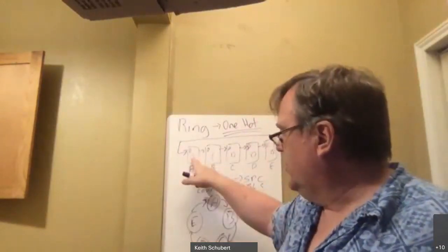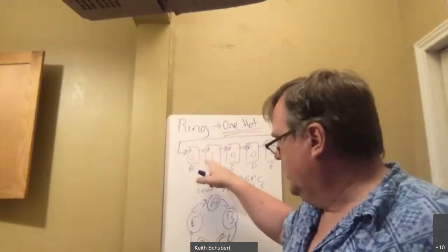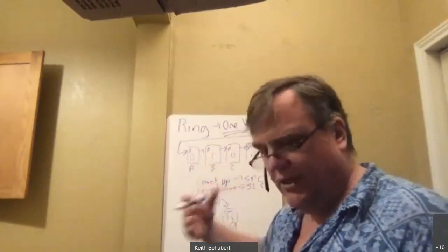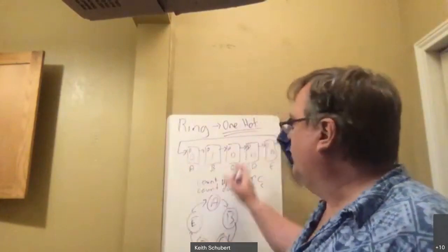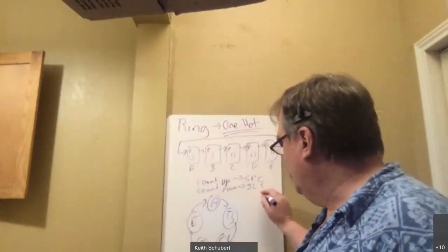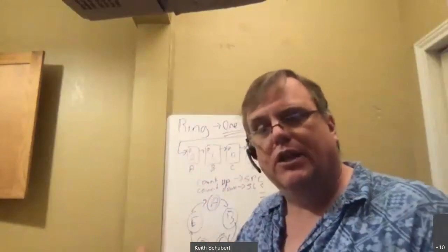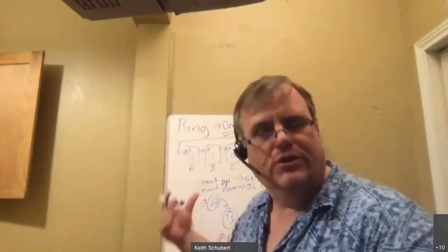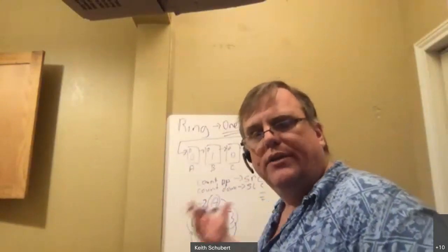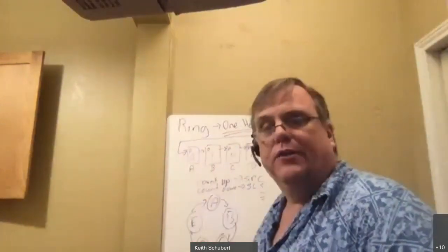So if there's a 0 here, there'll still be a 0 here after the shift. That's called an arithmetic shift. So those are the full types of shifts. For our system on a ring counter, it's only circulant though. I mentioned the others just for completeness, and when you get to those, you'll know what to do with them. All right, do we feel good with the idea of a ring counter?